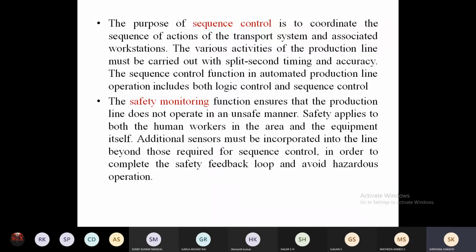The primary level of sensors will be used to safeguard the workstations. The secondary level of safety monitoring systems will be used for sudden events within the work volume of the robot. For example, within the work volume, the working space of the workstation, if a human intervention happens, at that time the work has to stop. The whole working has to be stopped so that it safeguards. That is the secondary safety monitoring system.